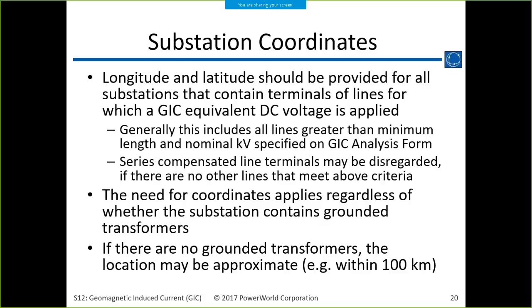And I guess the way it works, even if you're not modeling a DC input voltage on the lower voltages, it's still a network, and the simulator will still model the flow of GIC down into that network that originates from voltages on other lines. So it's not like the network's totally going away, but it could be a significant effect in some parts of the system. I think, mainly because of the fact that it often correlates with lower VAR resources.